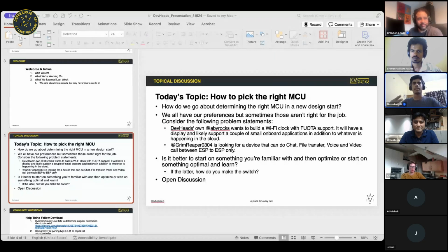So we have seen the processing, then the peripherals, then comes the power consumption. An MCU is highly likely used whenever your solution does not need such a great processing power, but it's a constrained environment and you want to optimize on both the processing and also the power. So power consumption is something to concentrate on and look at if that's what the solution demands, which is evident in most of the solutions like IoT or wearables, mobile devices, or something.